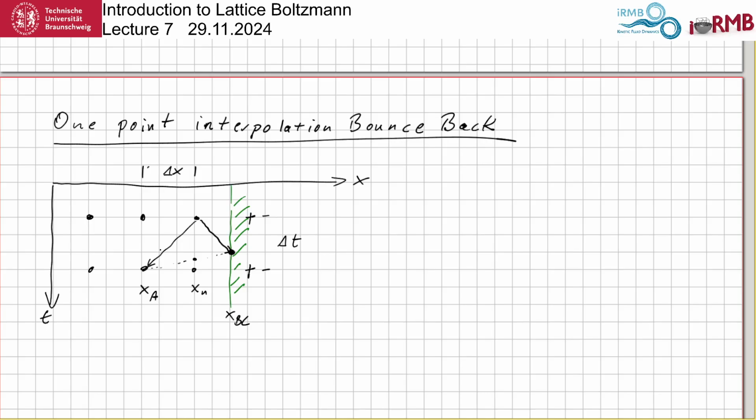And then, when you remember me saying that we should actually do a delay, which is not very accurate in time, you can already notice, okay, we can use a little delay here, and just keep this going down, and then we have a very nice boundary condition, interpolated in space and time. That requires only the populations in one node, and there's nothing that requires the distance to be in a particular setting.